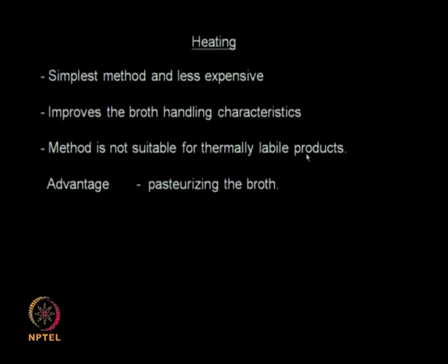If you want to pasteurize any food products, heating is a good technique because it kills these viruses or pathogenic organisms. But the most important point you need to keep in mind is whether the protein or metabolites present which you would like to recover are thermally unstable. Then in that situation you will not be adopting heating as a technique. Heating you can do in a batch operation, or you can also do in a continuous operation. In a batch, you take the material, the broth, in a large vessel and heat it and then cool it down and then send it to filtration, or you may do it in a continuous tubular type of arrangement.